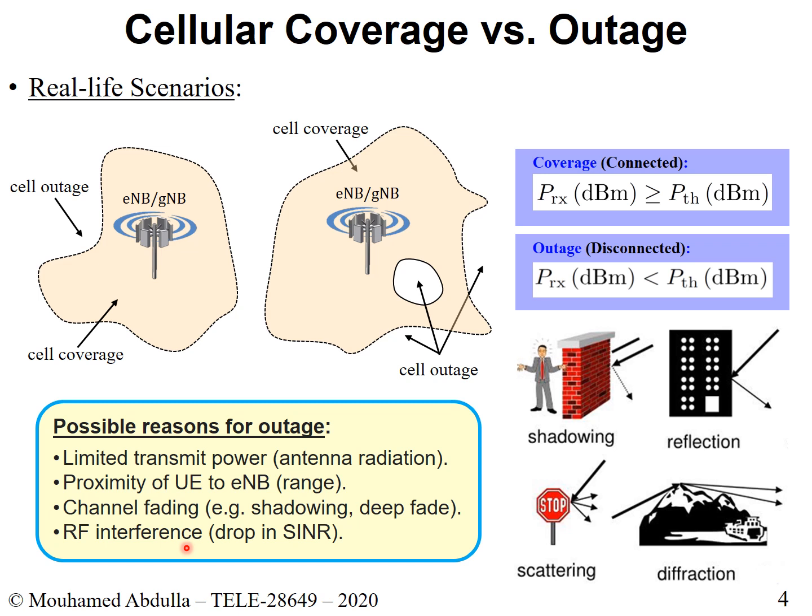So there are multiple reasons for interference, but these are some of the reasons. And if you have interference, what happens is your SINR, your signal to interference plus noise ratio, will drop. Right? So don't forget, you have signal on top, the good stuff, and in the denominator you have all the bad stuff. So you have your noise and you have your interference.